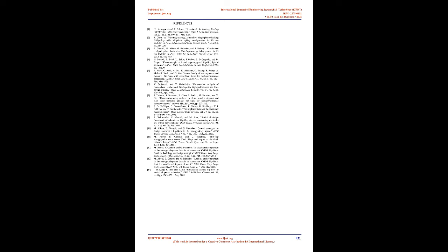When the data is held low while the clock continues to run, the energy dissipation of the DPSCRFF is reduced. However, if the clock is running and the data is held high, the DPSCRFF actually dissipates more power than for the full activity waveforms because of its output glitches. When the clock is held stable, no internal nodes change state and only the single data input gate toggles. The DPSCRFF therefore has low energy when the local clock is gated.